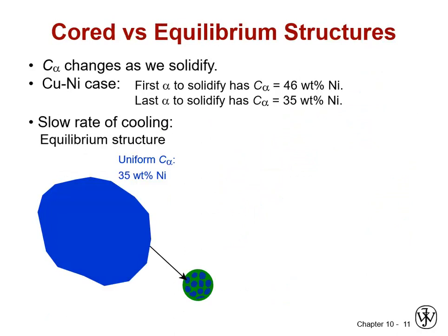Okay. We mentioned that phase diagrams only apply if we cool slowly and we keep everything at equilibrium. We're going to take a look at what happens if we cool too fast. And in this case, too fast literally refers to whether or not diffusion in the solid can keep up with the rate of deposition of new material from the liquid, and what will happen if it doesn't.